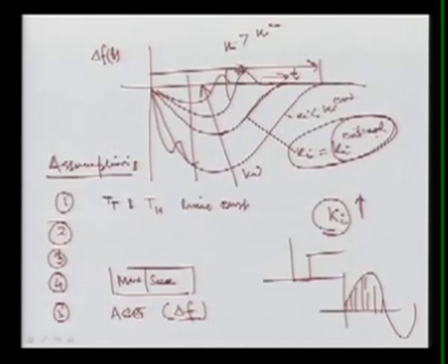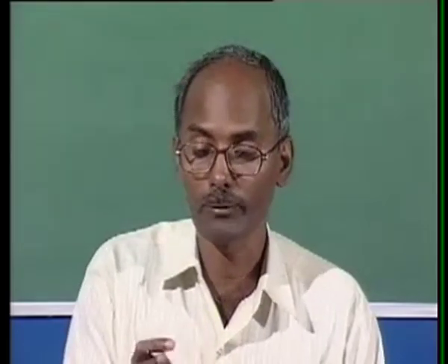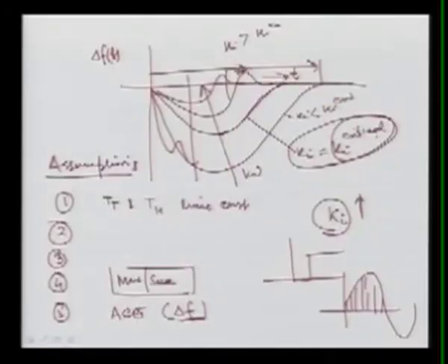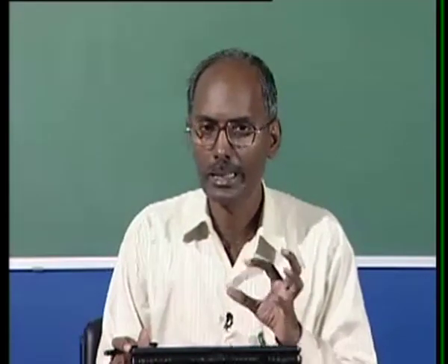If the sampling rate is relatively high compared with the fastest change in the response, then this whole analysis will give a good result. So we have to have fast sampling; the sampling frequency should be very high, then we can say this analysis is valid.